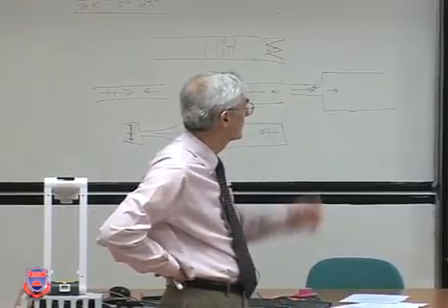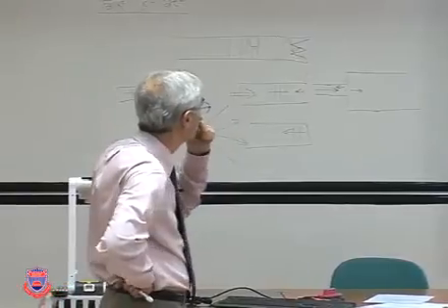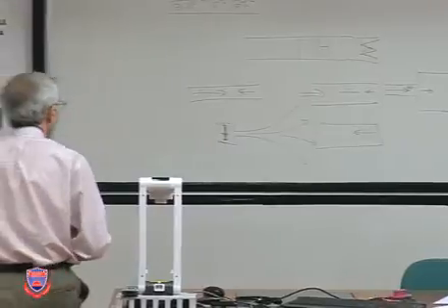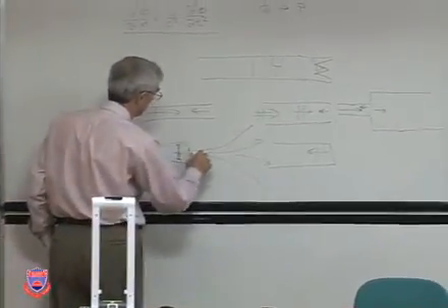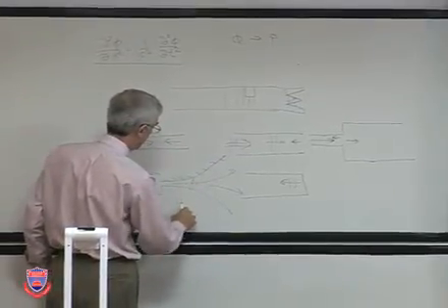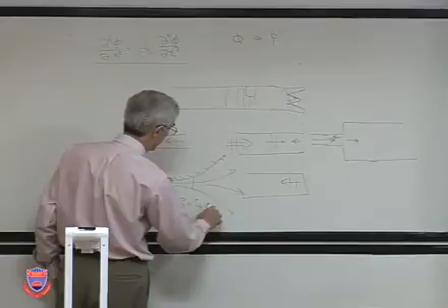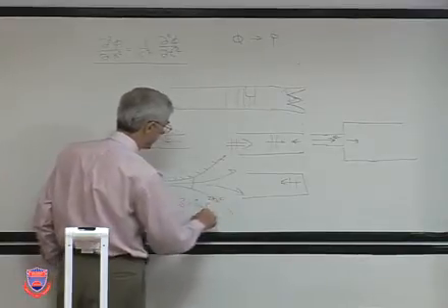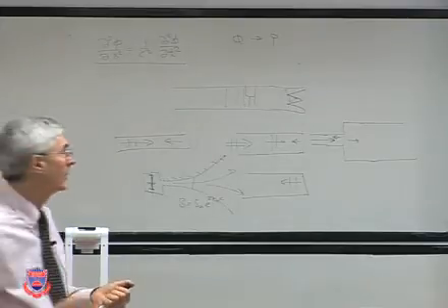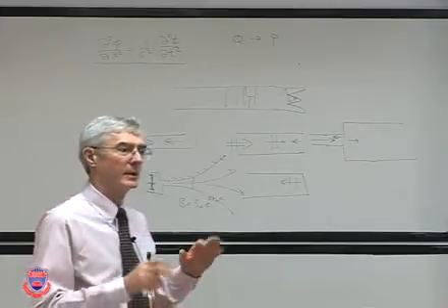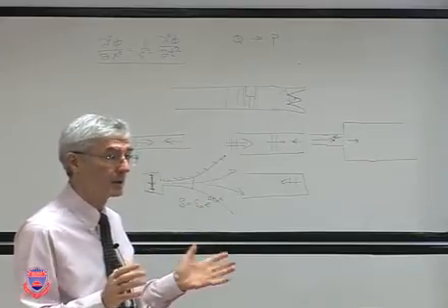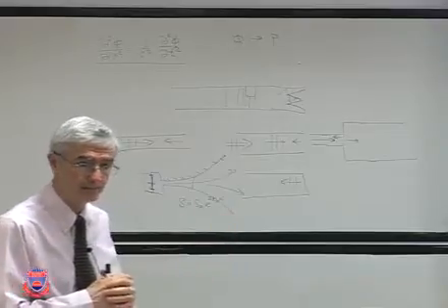Now, let's assume that the horn has an exponential variation. This profile here, the cross section, can be described by e to the 2k sub 0 x. There's an exponential increase up to a certain point, but we're now assuming it to be infinite. So we can say then there are no reflections from the other side, from the opening.